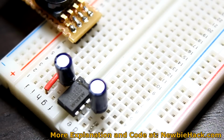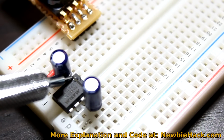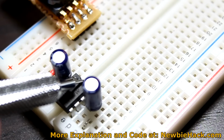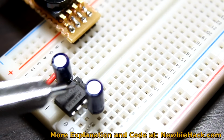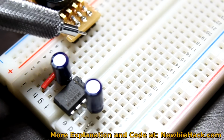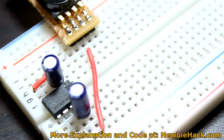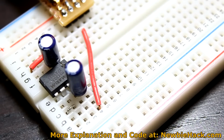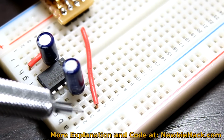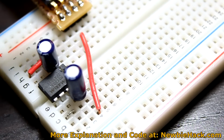We know that the output side of this chip is over here on the right hand side of the chip. This is the pin number 1 here, and a little dimple right here is showing you the orientation of the chip. And this pin here is the output for the regulator, and this is going to give me a 5 volt regulated voltage. This will go to the second pin, so let's go ahead and do that. And ground is going from this pin here. It can be either one of these 2 pins because the regulator always has the 2 middle pins as ground, to the pin number 3 here.